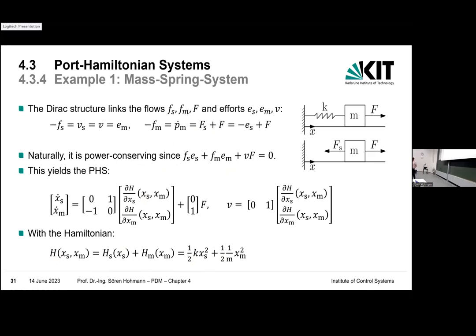So it gives additional structure to what you know from state-based systems. On the left-hand side we see the dynamics, the derivatives of the states. And the states are the partial derivative of the energy function of the entire system with respect to the states. If you think of equilibrium states in multivariate control, you can say your states are really the storage function derived with respect to the states.